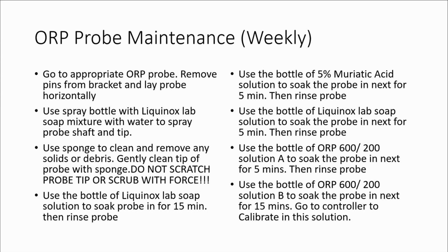Okay. So through this discussion, Kyle gave you the answer to one of the other questions that they're going to ask you to make sure you're still paying attention. And that had to do with single point or double point calibration. So you want to explain that again? So single point calibration, you only use one cal solution. Dual point or triple point calibrations, you use just like it sounds. You're either using 2 or 3.